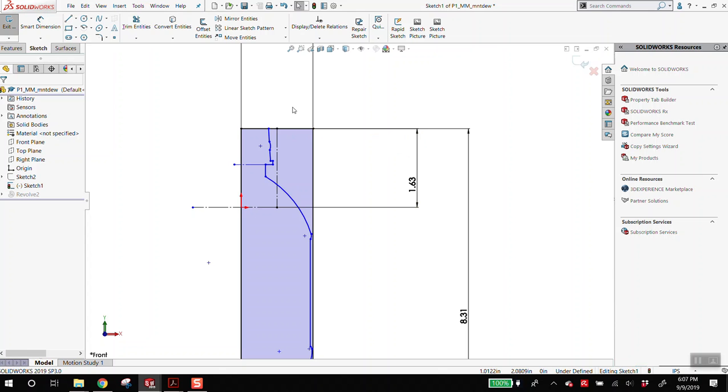This is a good example of what I want to see in all of your master sketches: having this bounding box, having the height of the bottle dimensioned from the origin being at the neck finish, and then from the neck finish to the top of the cap being dimensioned to fix that bounding box. Is that absolutely clear to everybody? I see faces looking down.